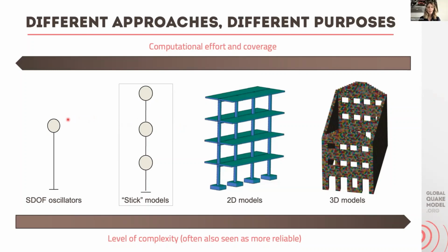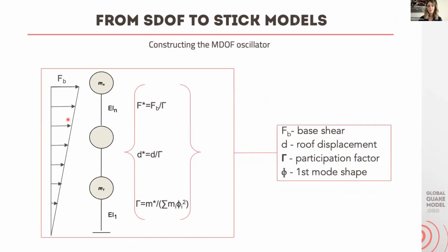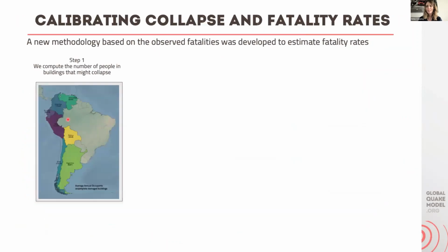Thanks, Victor. Yeah, I would say if you're using the vulnerability modelers toolkit, especially as more of a basic user, maybe you have a 3D model where you've done a pushover analysis and turned it into a capacity curve, and you're using that to produce fragility and vulnerability models. If you can run some dynamic analyses on your 3D model, it would be worth comparing those results with what you're getting from the single degree of freedom system through the vulnerability modelers toolkit, at least in terms of the peak displacements, as a first check.